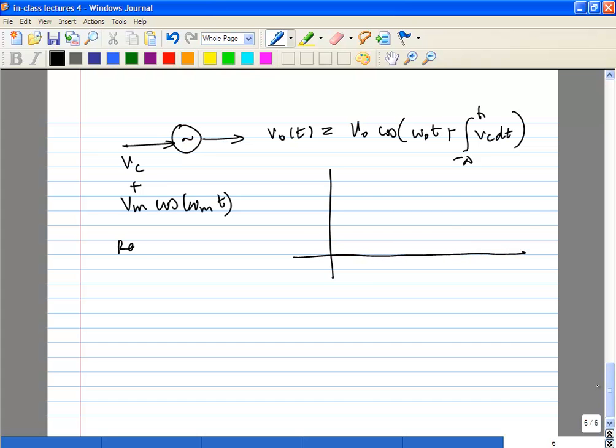you can look at Razavi section 3.2.2, that gives you an accurate expression for what the values are, but if you do this, you will get the sinusoid V naught cos omega naught t, but you will also get two equal side bands, at a spacing omega m, and this is valid for omega m much smaller than omega naught.